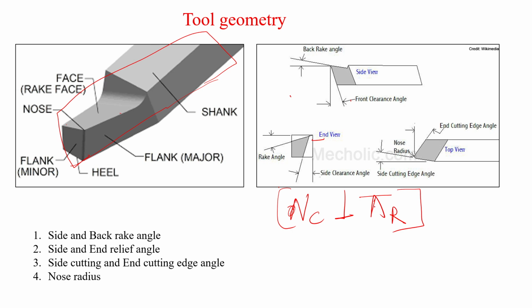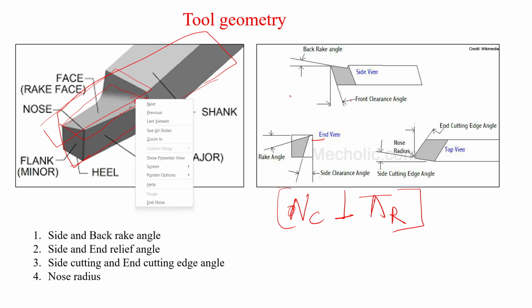See, if the rake surface is somewhat tilted, and the reference plane is like a parallel plane, then there is some angle between the reference plane and the rake surface. This is called alpha, which is the rake angle. Understood? Okay, do you have any doubt? No. Fine. So there are different terms for representing this rake angle.